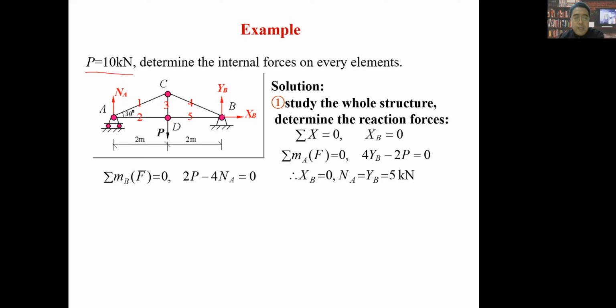And at point B, it is the fixed pin support between these two members and the frame. You know the frame never moves, right? It's fixed all the time. Because it is a fixed pin, it has two reaction forces, one is X_B, another is Y_B.